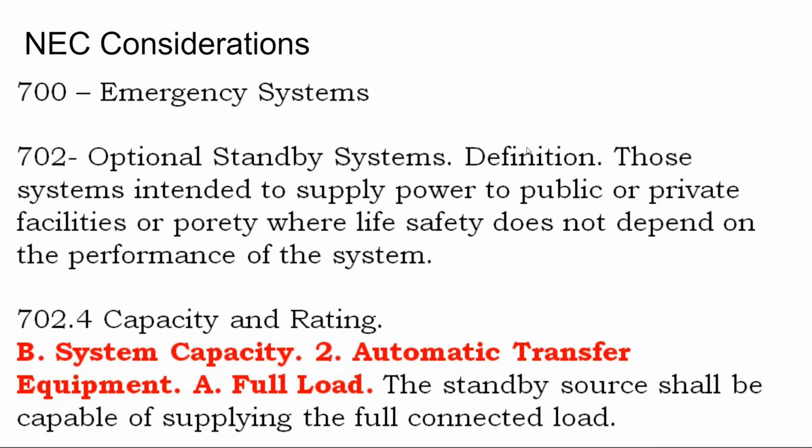Yeah. Property is what it should be. So intended to supply power to public or private systems or property where life safety does not depend on the performance of the system. So yeah, there's a difference between standby systems and true emergency systems in the eyes of the National Electric Code.